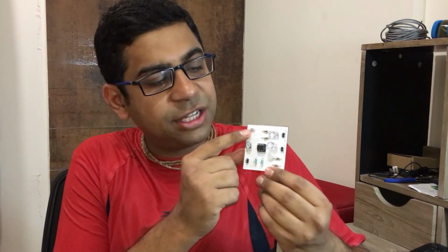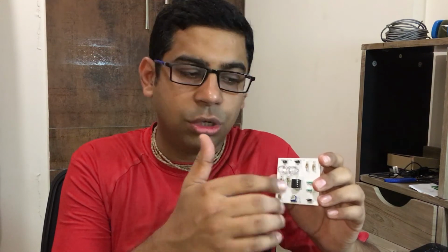The board that we will be talking of today is an LDR dependent light intensity detector. So this board has an LDR, a light dependent resistor, and it has two outputs for us. One detects if the light is below the given threshold or above the threshold. So it's a low light intensity detector and a high light intensity detector. The light intensity threshold is set through the potentiometer that we have over here. It has an input supply of 5 volts and the two outputs that we had talked of.